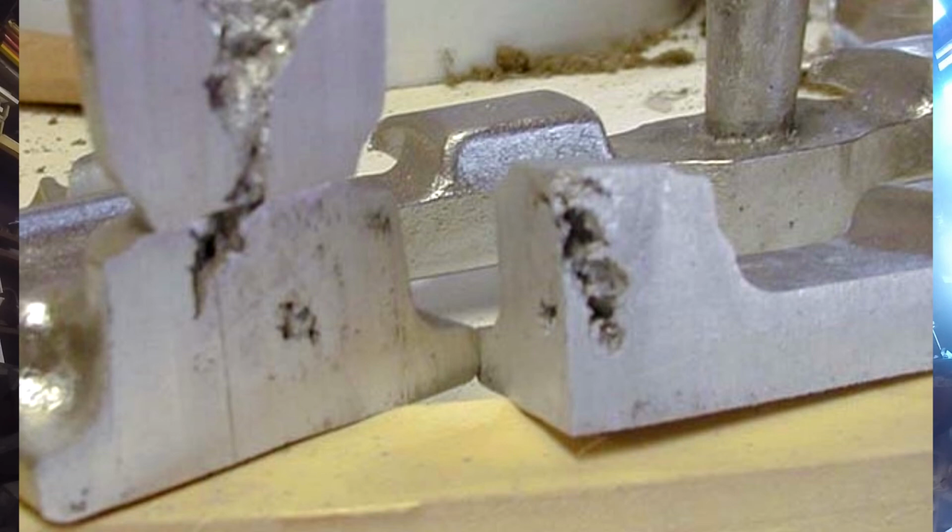Now notice how it was about the middle of the metal that the walls of that casting did solidify, and as the walls solidified and drew molten metal into the crystals, and everything progressed towards the center line, this is what happened. This is the shrink that took place after all the metal had been used. And you had this big void left over.